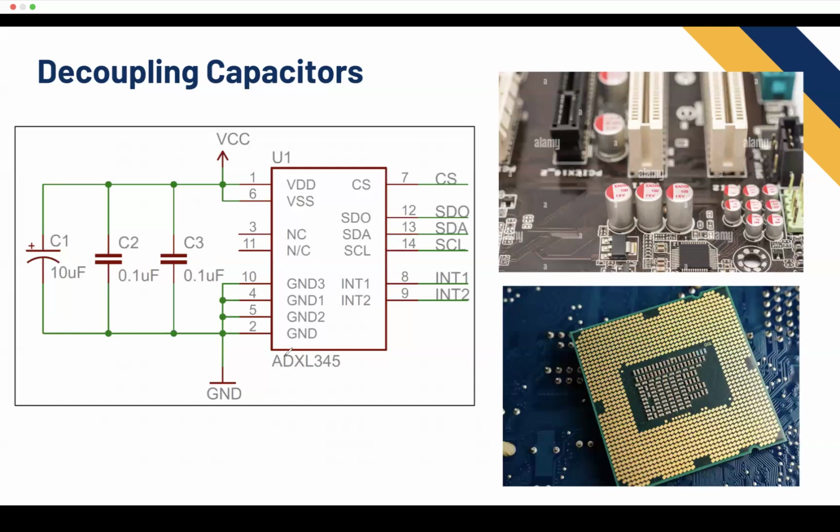AD is typically an Analog Devices component, so they probably produce this. I don't know what the ADXL345 is though. Something digital. You see it has an I2C bus and then 2 interrupt pins. Oh wait, it has I2C pins, but this is a chip select and a serial data out, so it's actually SPI.